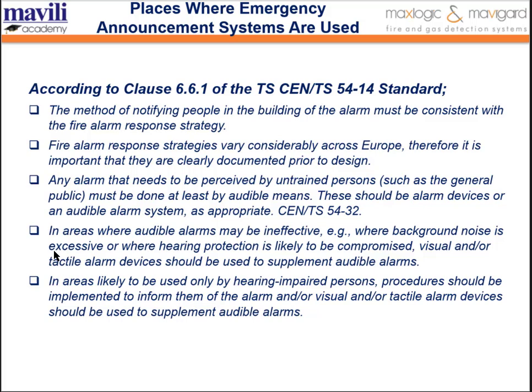Also, in areas where audible alarms may be ineffective, where background noise is excessive, or where hearing protection is likely to be compromised, visual and/or tactile alarm devices should be used to supplement audible alarms. So in areas likely to be used only by hearing impaired persons, procedures should be implemented to inform them of the alarm, and visual and/or tactile alarm devices should be used to supplement audible alarms.